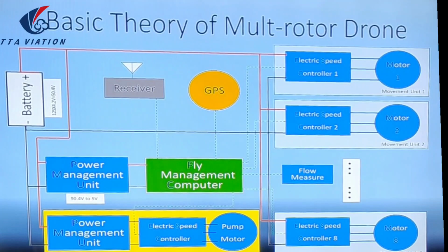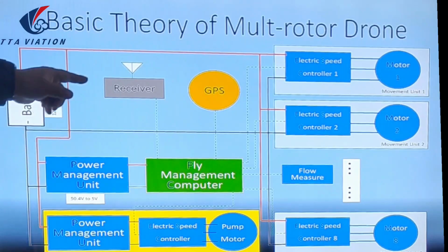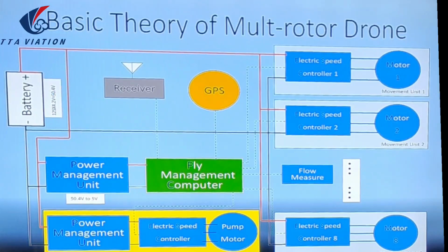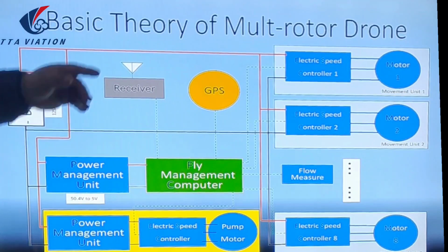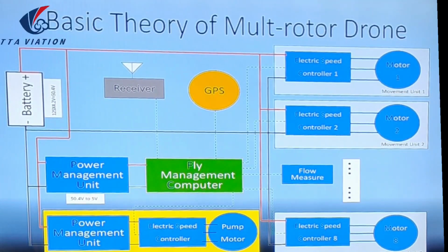The motor uses three-phase power in its work, and like a normal three-phase motor, if we want to change the motor's spin direction, we can just exchange any two wires. Then the motor's spin direction is changed.